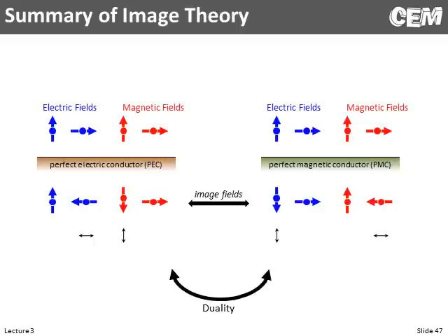And to summarize it, we can have two different kinds of interfaces where there's this symmetry. We can have perfect electric conductors and perfect magnetic conductors. And they're a little bit different. And later on, we'll see how to actually build those into models. But imagine you have a device here and two different fields on either side. If the normal components are oriented this way and the transverse components are opposite, and the magnetic fields have that symmetry, if your device would produce fields like that, you need to use a perfect electric conductor.